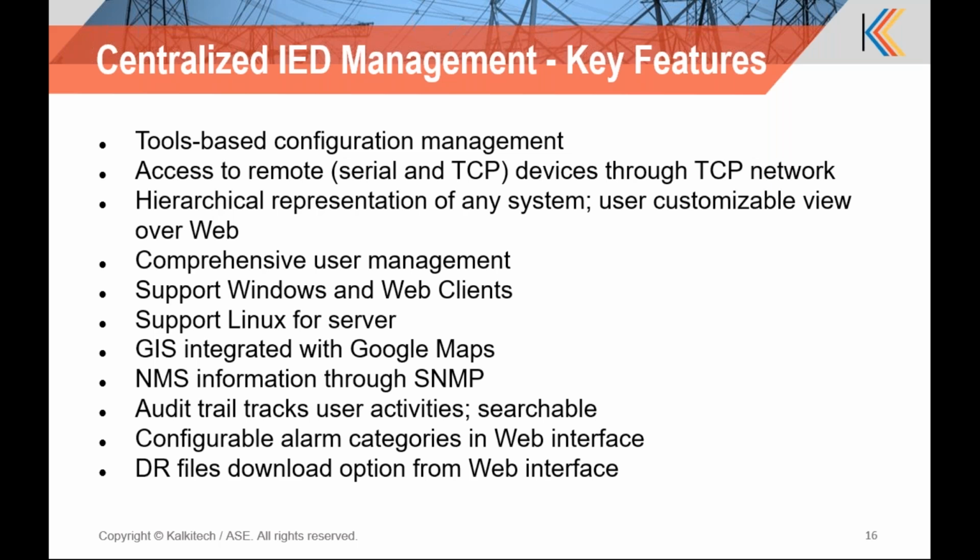Audit trail is available to track details of user activities. Multiple security levels are available. Then configuration alarm categories in the web interface. Then disturbance record or fault file download options from web interfaces are available. So centralized IED management using PSCS is one of the key features we offer with this package.